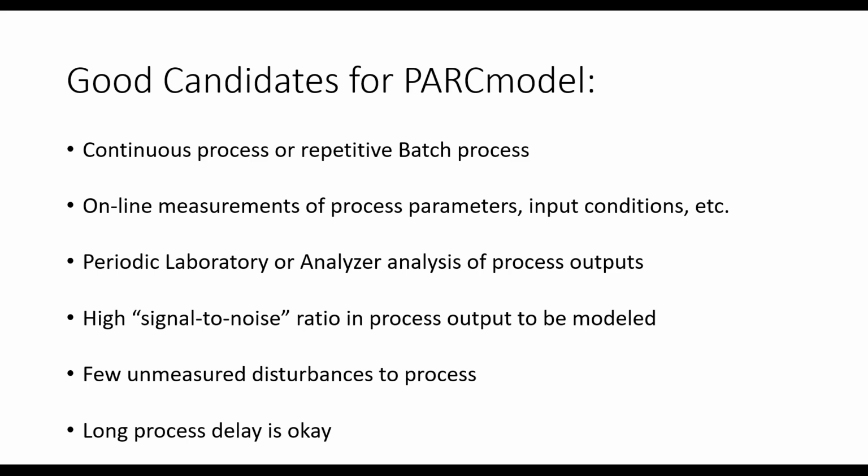Also, and of course this is where the model becomes so useful, is if you have periodic laboratory or analyzer analysis of process outputs. So if you're continuously measuring the inputs, but your process output has a quality measurement that's only measured by a laboratory every 1 hour, 2 hours, 4 hours, then the beauty of a model like this is it allows you to predict the result of that periodic analysis in real time, and have real-time feedback in between the sample analyses that the laboratory or the periodic analyzer runs. That's what's so powerful about it.